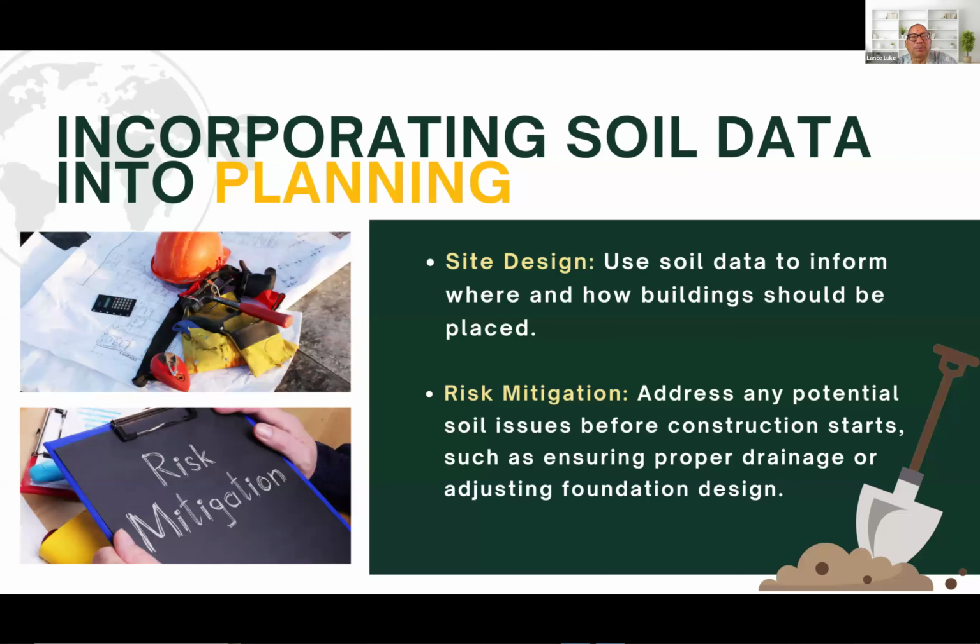Incorporating soil data into planning. Site design: use soil data to inform where and how buildings should be placed. And then there's risk mitigation: address any potential soil issues before construction starts, such as ensuring proper drainage or adjusting foundation design.